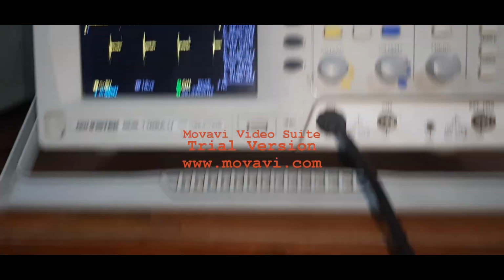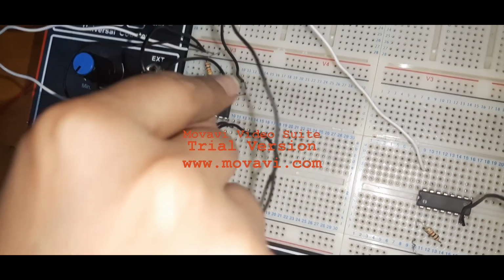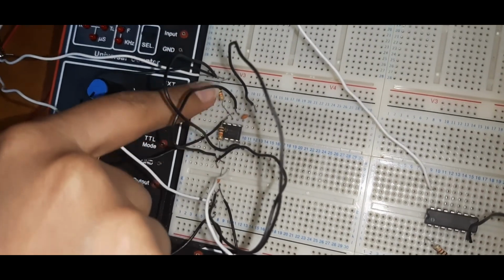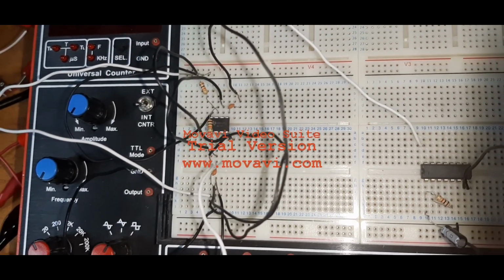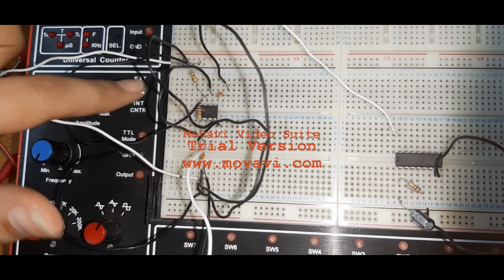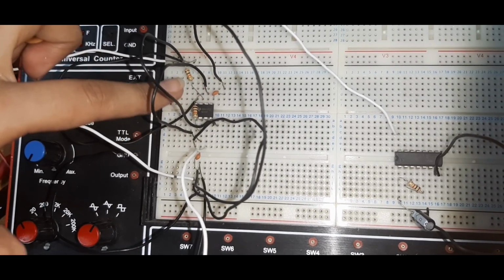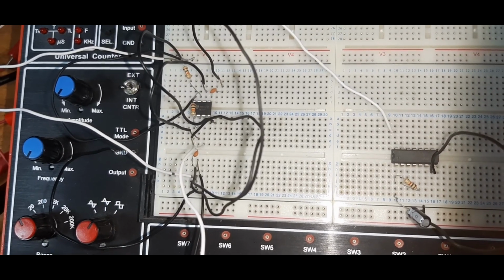So this capacitor is used to maintain the frequency of oscillation, and this capacitor is used to refine the output waveform, and these two resistors are producing the duty cycle of the square wave. So if I want to change the duty cycle of the square wave that is generated, then I have to change the two resistor values. These two resistor values define the on and off time of the square wave, which is the time period of the square wave.